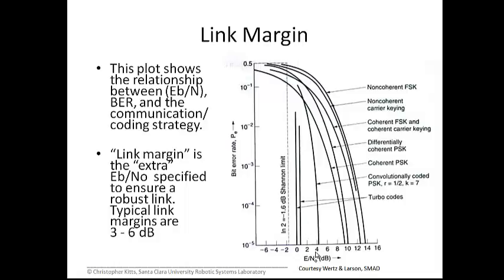And you can go through all sorts of trade-offs using these relationships captured in this particular plot. I can do the same thing, say at 10 to the minus 4 or 10 to the minus 5. I will tell you that it's not even on this chart, but 10 to the minus 6 is kind of a benchmark for most communication satellites. Certainly the ones that I've worked on, 10 to the minus 6 is considered an acceptable bit error rate, and probably even lower than that currently. And this gives you that relationship between acceptable bit error rate and the signal to noise you need to achieve it as a function of your selection for modulation and data encoding.